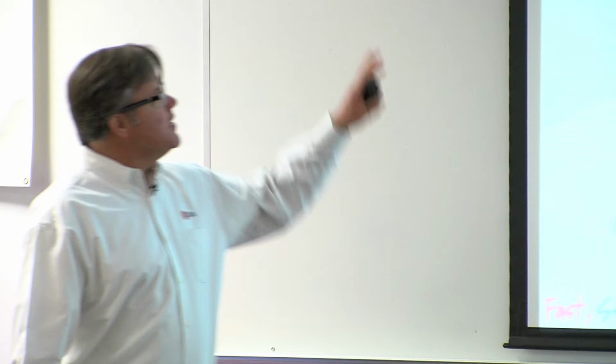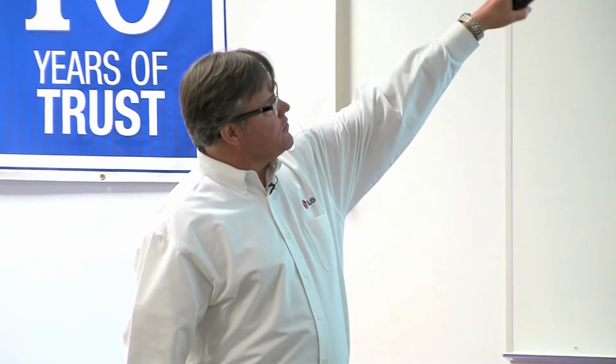It was invented back in 1982, with the first inverter-driven system in 1990. Just to get a sense of where we're at, raise your hand in this room if you know what an inverter drive is. We've got some folks yes, some folks no. No big deal. An inverter's like a gas pedal for an engine, and lets it go faster and slower, is all it is. Simultaneous heating and cooling of VRF came in 1992, and the first 410A system in 2003. It didn't get here until it was already 15 years into the making, and then it's just recently been re-engineered with new stuff.